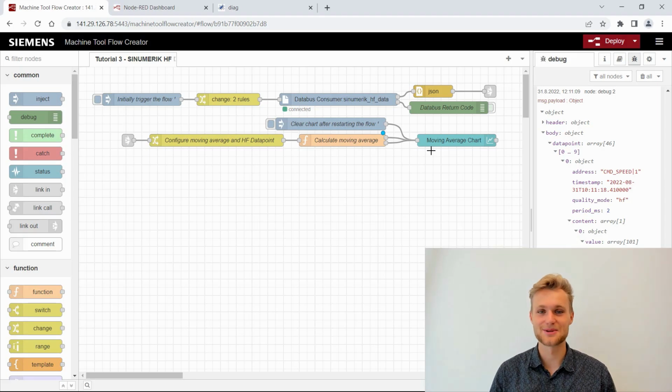Hi, welcome to the third episode of the Machine Tool Flow Creator tutorial series. Last episode you learned how to work with low frequency data on the SINUMERIK, and this episode will be about how to work with high frequency data. We will program an application where we read high frequency data from the data bus, and then we calculate a moving average over it, and in the end we plot it on a dashboard.